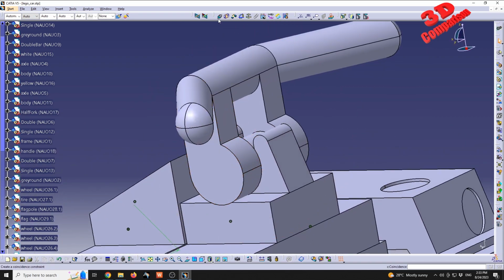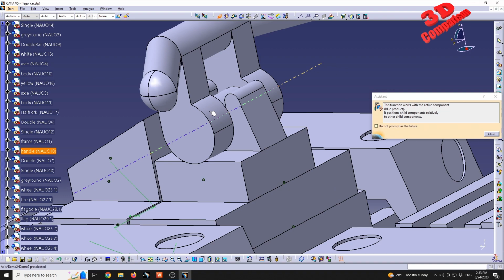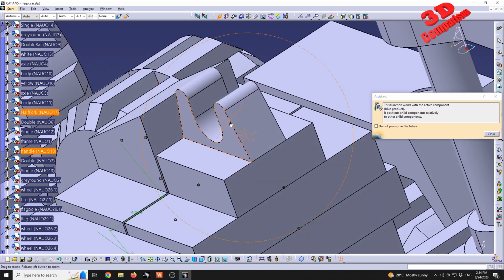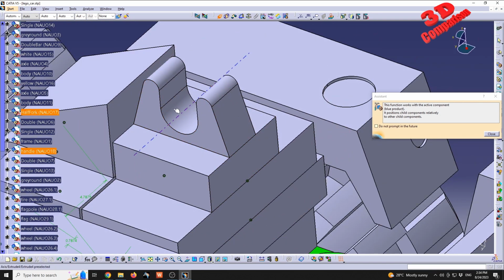That means that we can go to the steering wheel, which for the axis of components in CATIA, you will always find the axis on the width of the circle. So we see the half circle over here, okay, and if I move my mouse on the width of that, so we see the profile and this will be the extruded direction, we are gonna find the axis over there. And I know that the axis over there should be coincident with the axis in the interior side. So again, I'm moving my mouse cursor within the middle area.